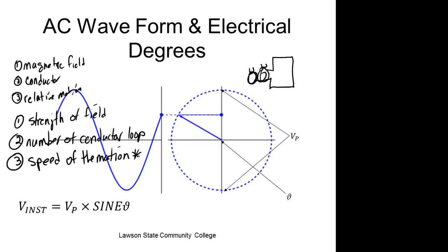Jump your car off, crank it up, and if the alternator's running, if it's got any current available at all, in fact, it's going to generate itself, it should go up to over 14 volts. If it's coming up to 14 volts, then that means your alternator's good, and your problem's in your what? In your battery.